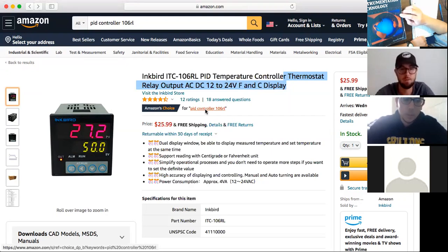So this is a manual control, where you control how much peroxide is added. What we were talking about here is automatic control. The PID controller is automatic control. In your line of work, it would be: I want my flow rate to be this, and this sensor will measure the flow rate in real time, and my controller will change the percentage of that chemical, how much is added.